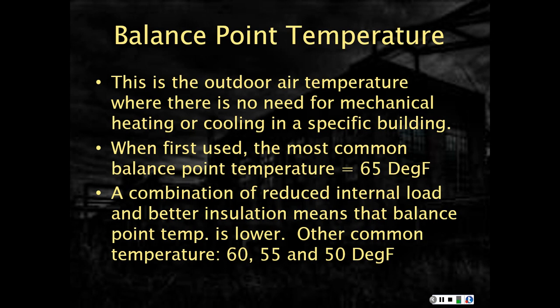So we just talked about the balance point temperature. 65 is the most commonly used, and if you go to tables nowadays, most degree day tables are still based on a balance point temperature of 65.